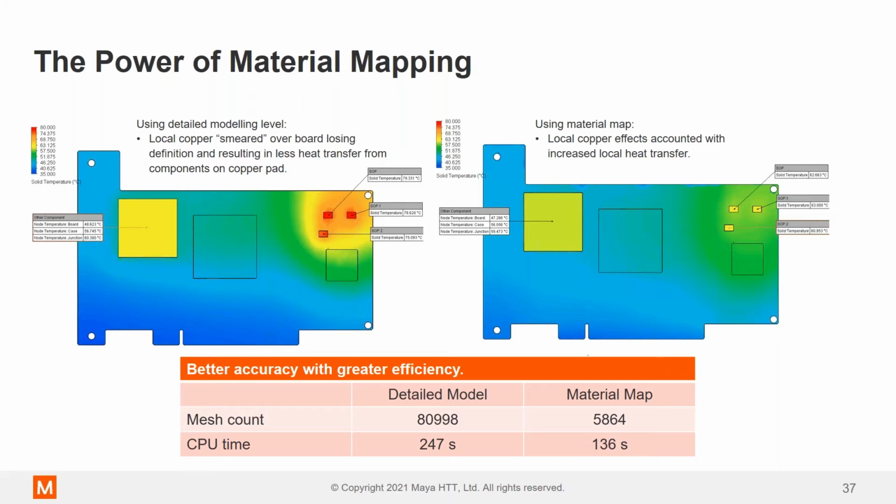That's a pretty big difference in temperature, 17 degrees C. That's huge in the thermal modeling world. So it's really critical to get the component and the PCB modeling right in your thermal analysis, because that's where the heat is generated. If your conduction paths and your convection paths are not correct, the rest of the simulation as you zoom out won't be correct either.